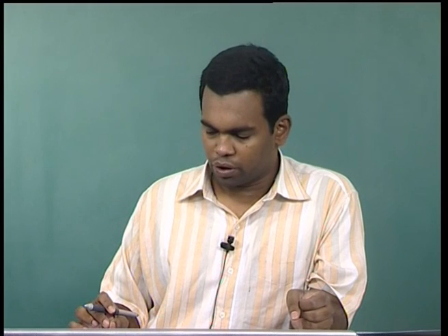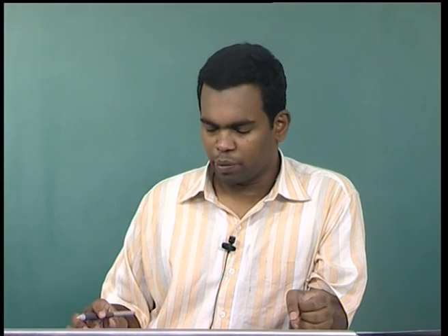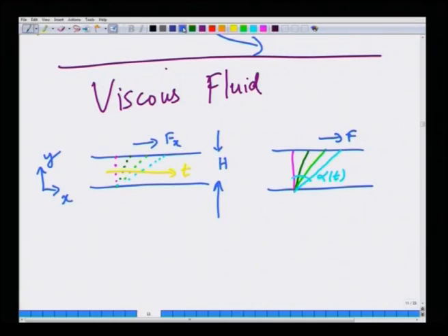Now, if you apply a given stress, if I have a given force F of x, and if you apply a given stress tau y x, which is force divided by unit area of the top plate, then these lines will continue to deform. So, we cannot say that the stress is proportional to the angle, because you can get a larger angle provided you are willing to wait long enough.